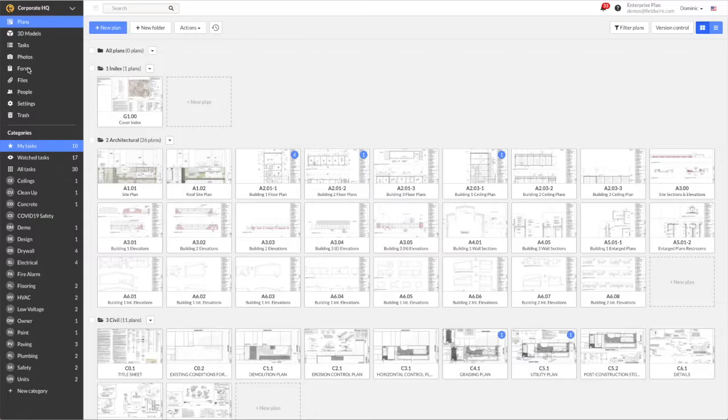To start off, we will review how custom form creation and editing can help you stay compliant with safety regulations put in place by your governing authority or GC during the time of COVID-19. For those of you not familiar with Fieldwire forms, these allow you to build any type of form with different types of data inputs. To build these forms, you'll want to use a desktop and will need admin access on the project. From my desktop, I will start off by going into the Forms tab in my project.